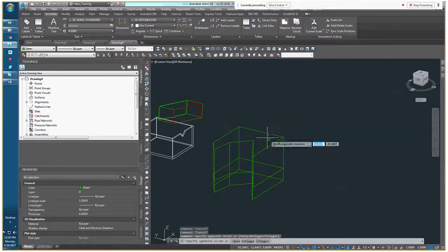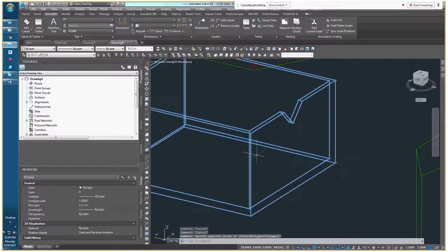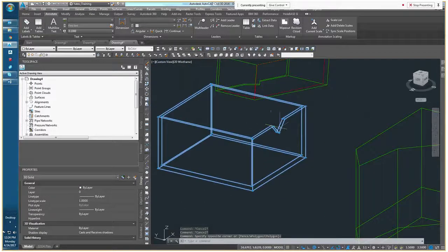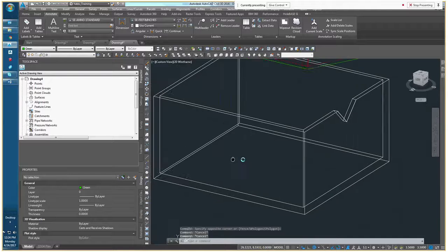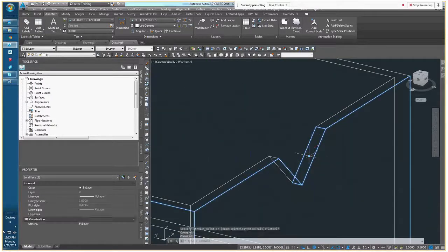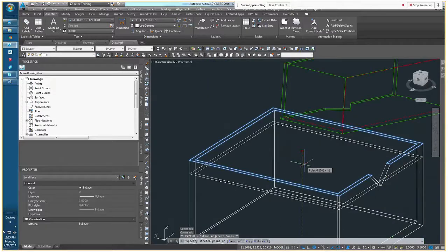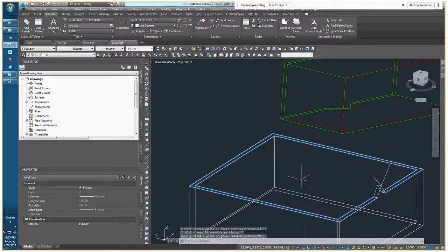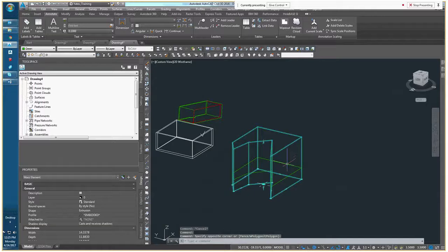And on 3D solids, selecting the 3D solid gives you a look that looks like this, where each of the vertices is highlighted in these dark blue grips. But if you were to hold down the control key and then select on a 3D solid, it actually allows you to select and then manipulate through the grips various faces. Everybody seeing how that works? So with a 3D solid, I can select individual faces and manipulate them individually. And that's just handled slightly differently than on the massing element.